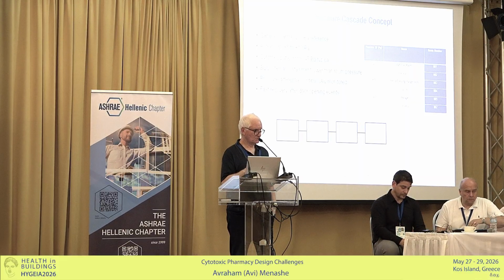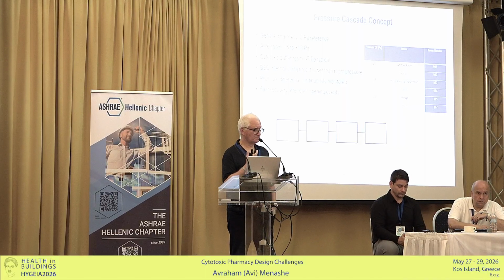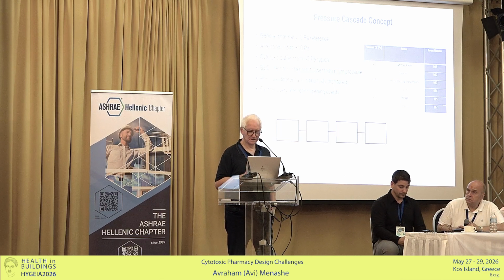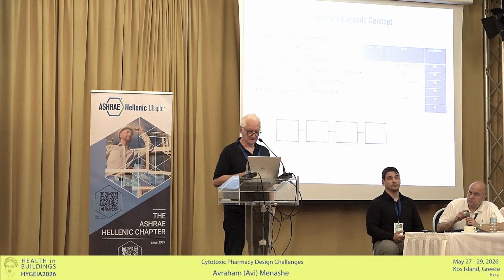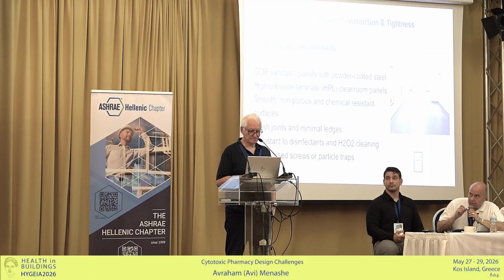If you have minus 40, for instance, then it creates the opposite flow from the BSL to the room. You don't want that because you want to protect the workers. Therefore, we normally reduce the condition to minus 30, to minus 27, but the most important thing is to keep the cascade of pressure between the different spaces in the pharmacy.